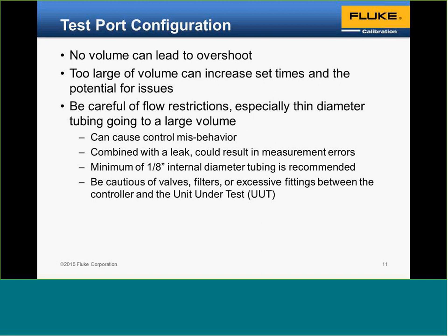Start your pressurization with the valve closed and it sees a small volume. Then it controls in one fashion. If you open the valve on it, that will potentially interrupt the algorithm. The opposite works in reverse. If you start the excursion with the valve open, it goes, okay, I have a really large volume here. I can meter very quickly. I've got a large volume to fill. I'm less likely to overshoot. Halfway through, you go, oh, whoops, I don't want to pressurize all that. You close the valve.